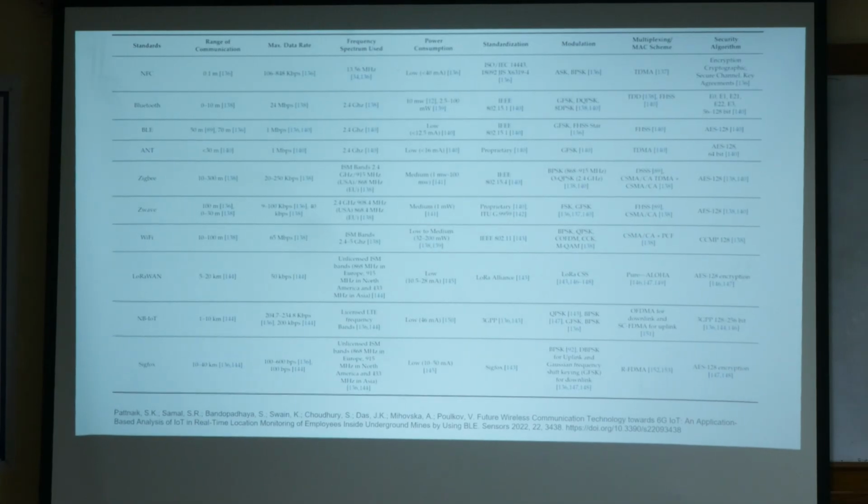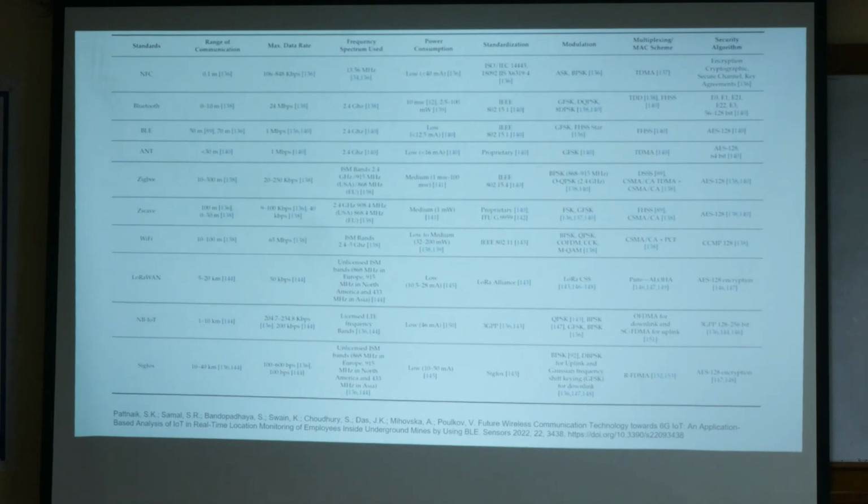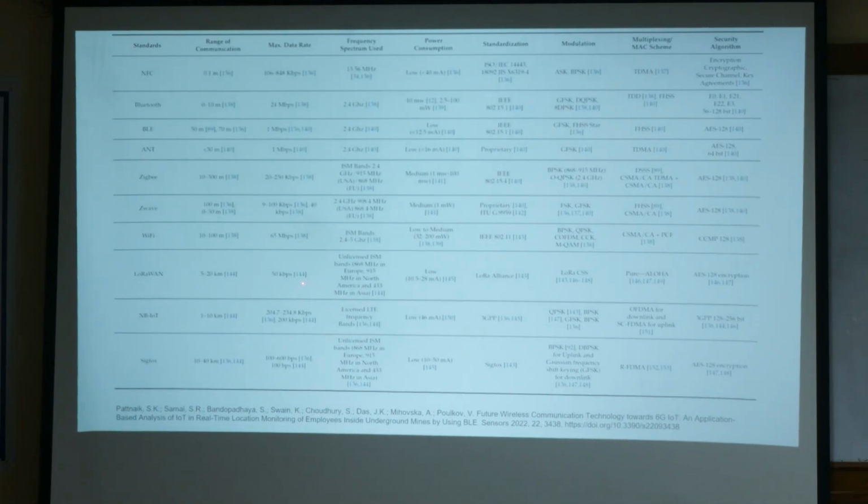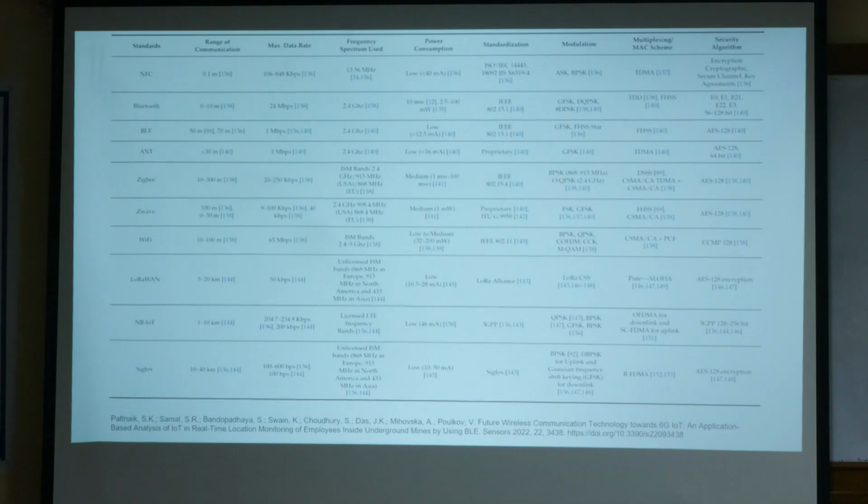And if the user density keeps increasing, then collisions might happen and your data might not go through, right? If you look from the data point of view, this transmits at a maximum data rate of only 100 to 600 bps, and this is 30K. This is one advantage why people are moving towards LoRa rather than Sigfox. The data is very small compared to LoRa. It is in bits per second only. But this is sufficient for IoT applications.